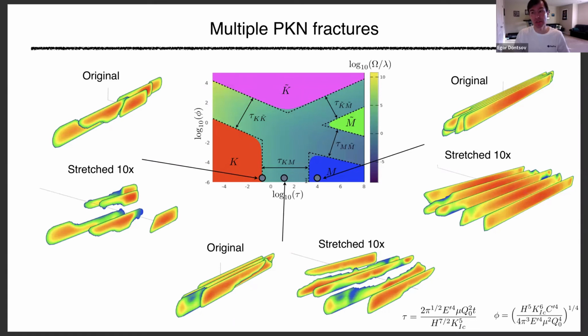Once you add viscosity, the situation is very different. Now we have all nice and equal hydraulic fractures. They are shorter, because if you have everything the same and add viscosity, you add more resistance, but they all have similar geometry. Near the fracture tip there are some distortions, and we also saw some distortions for the radial fracture. But globally, they are the same.